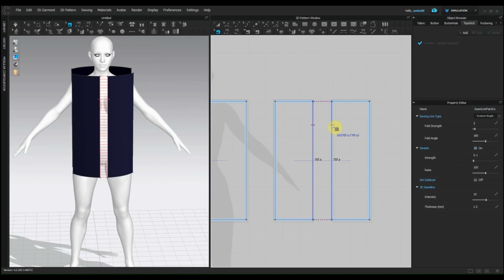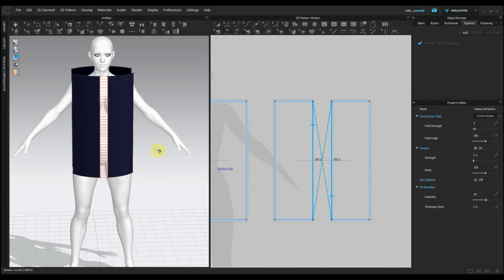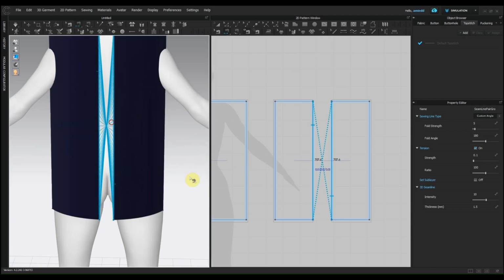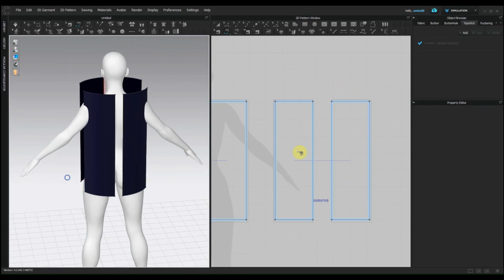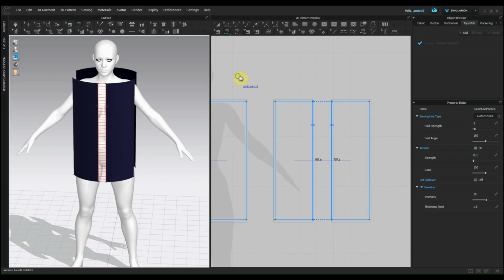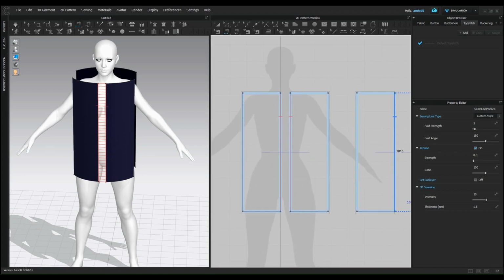Okay, I'm going to show you a quick common thing that happens when you do the 3D sewing. We're going to come in here and just delete these two stitches we did for the back. You come next to the sewing machine right here to edit. I'm just going to delete the ones we created, and then I'm going to do the sewing again, the top and the bottom. You'll see it's indicated by a giant X. You do not want to do that because the two patterns will actually be flipped and squished, and when you run the simulation, the pattern and the fabrics will be all twisted.